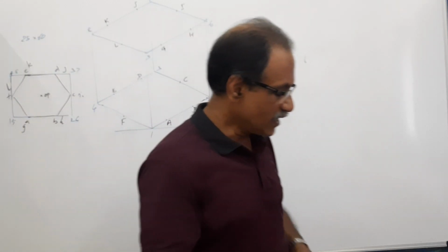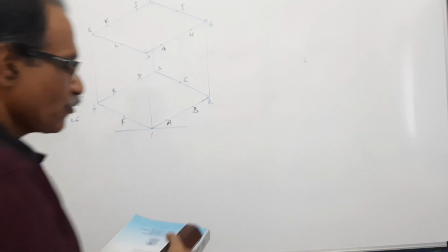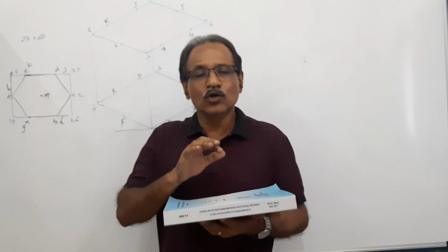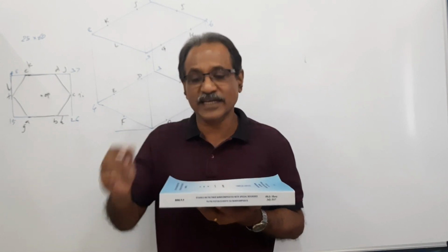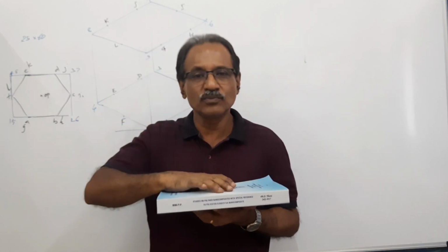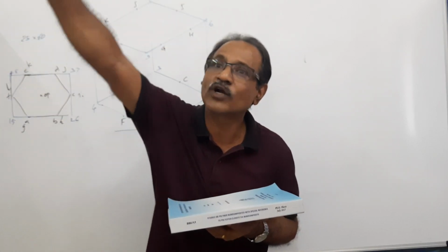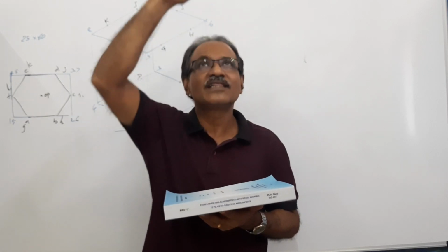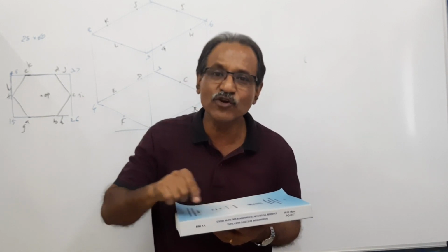Now, please listen. When an object is here, this is a very rough explanation. I will come to the correct explanation later. This is the box which you have drawn in the first case, 60, 40, 20. For the time being, assume that this view is elevation, this view is plan. You know that isometric view is a view from a corner at a height. I repeat. The view from the front is equal to front view or elevation. The view from the top is equal to top view or plan. Assume for the time being that isometric view is a view from a corner at a height.